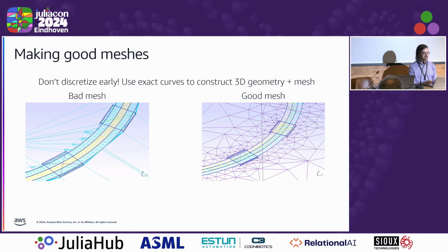And what I want to zoom in on here is the meshing. So a mesh in the finite element method is a discretization of space that allows us to turn Maxwell's equations for electromagnetism into a numerical linear algebra problem. And the quality of the mesh strongly affects how well-behaved that problem is, as you throw more resources at it: its accuracy, its convergence.